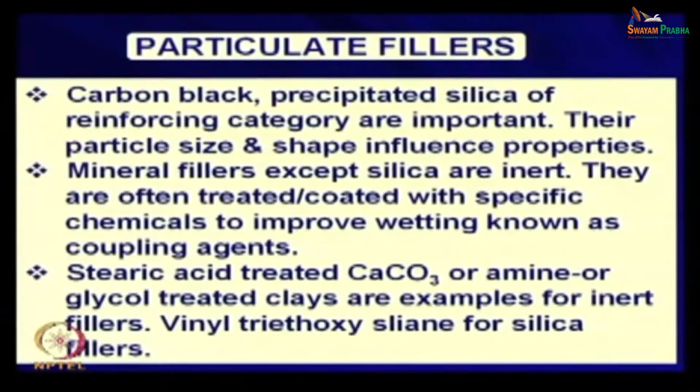Examples for particulate fillers: carbon black, precipitated silica, reinforcing category. I shall discuss the details of carbon black and silica fillers later, when I discuss rubber products. And again, to increase the interaction between a filler and the polymer, sometimes these fillers are modified a little bit.